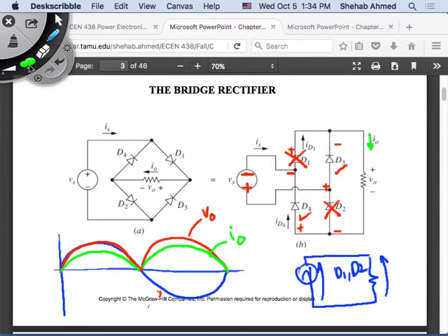And note here, this is the way we draw it, the way the power electronics people draw the bridges is more self-explanatory, in my personal opinion. Because look at the diodes; they're both pointing up. What does this tell you? Current can only flow out this way. It tells you the output is DC. You cannot have current going back. Current will never come back into the circuit, into these diodes, right? As soon as you try to push current back, the diodes disconnect, right? So versus here, it's more difficult to see that, in my opinion.